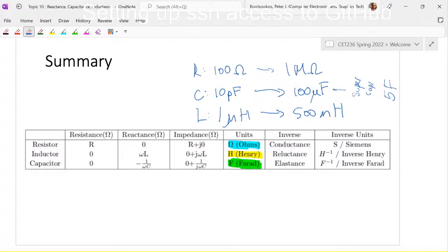Oh, I've forgotten how to read these. They have a bizarre way of marking them. I think it's 47 picofarads, but I'd have to look it up. Probably in the nanofarad range, and that one's in the microfarad range, so there's a factor of 1,000 between them.